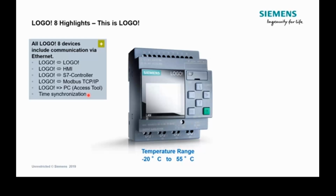When we have a diagnostic event occur within the system, it makes a lot more use to the engineer if the alarming information has timestamps and all of the timestamps are synchronized across the system. Then we can look at that alarming information and diagnose chronologically the sequence of events and work out what caused the problem in the first place. And that's why we employ time synchronization, so we can utilize the NTP time protocol to synchronize clocks of LOGO! with other devices or even just within a network of LOGO!.